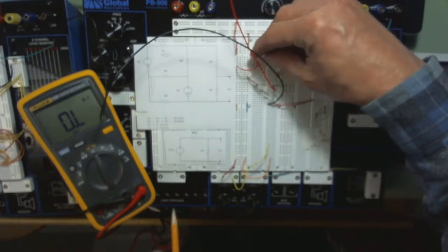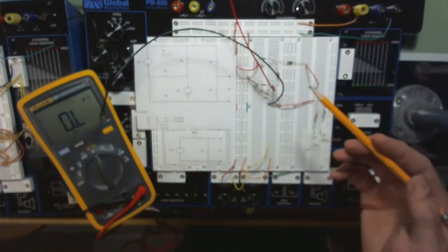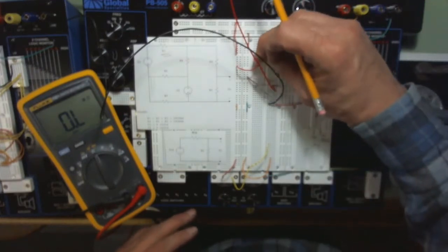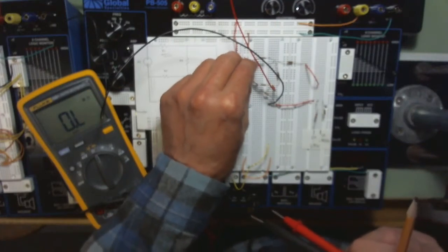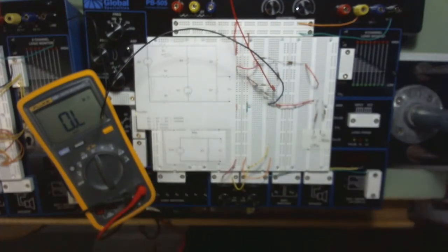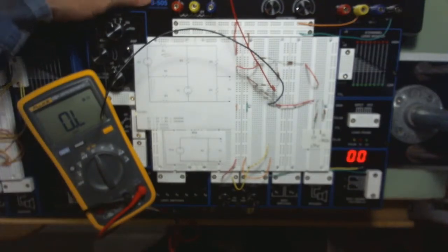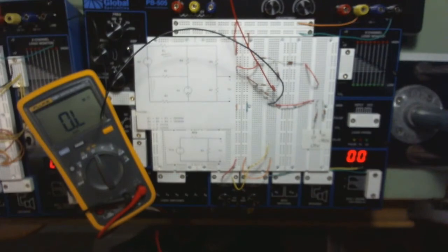I'm not going to do that for each one, but just a quick recap: do it with the power off, and you have to unhook at least one end so that you don't measure the equivalent resistance. I'm not going to belabor it again. We've got bigger things to think about here, although that's certainly important. Well, with that, let me go ahead and power this up. And I'll have to power this other one up, so I should have my sources then. Let's make sure that that works out.